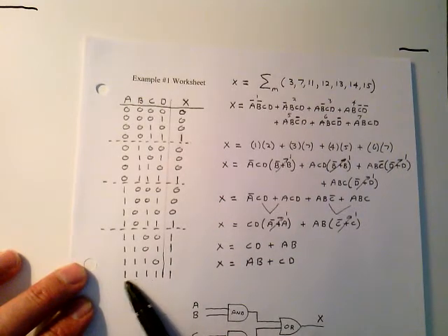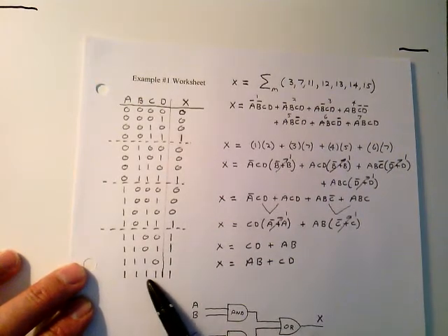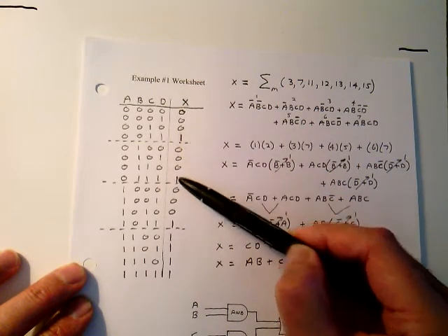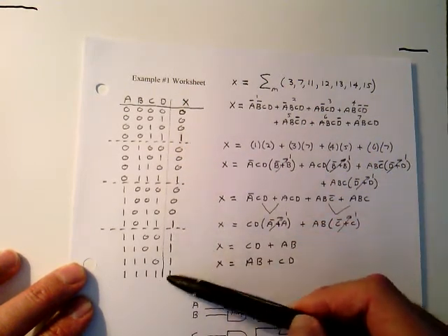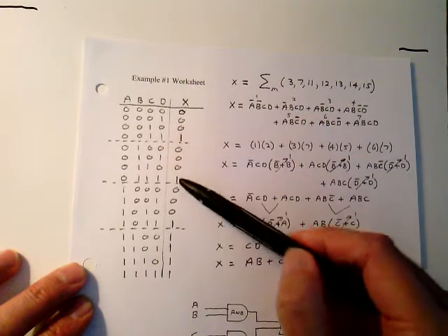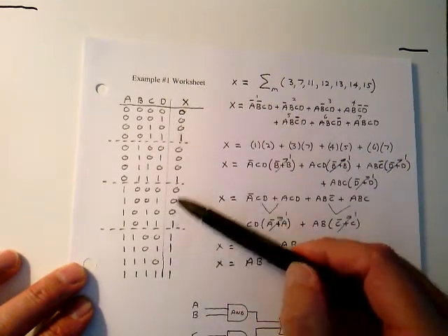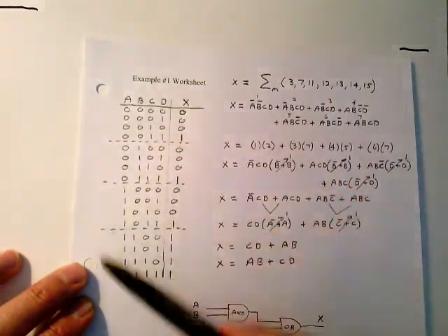When A and B are active, at the same time C and D are active. So our fundamental products are this one, this one, this one, this one, here, and here, and here. Notice there are 1, 2, 3, 4, 5, 6, 7 fundamental products, and by default the other ones are zeros. Now we have our truth table.